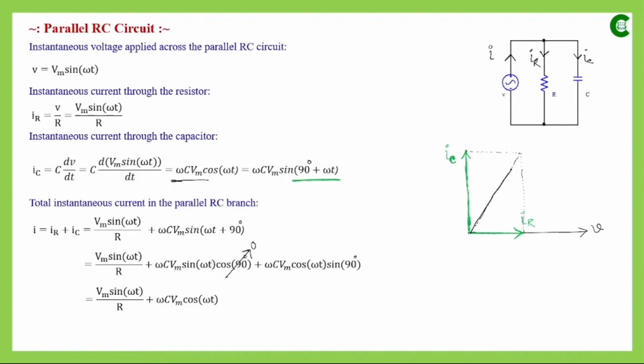So this will be the phasor of total current I. Now here we can see that this total current I is leading the applied voltage V, but the phase difference between I and V is not 90 degrees, rather it is less than 90 degrees, and let's mark that as theta. So here the expression of current will have plus theta as I is leading V.